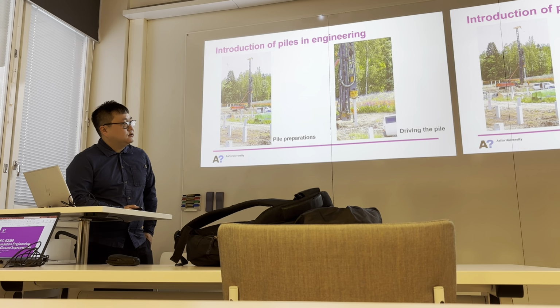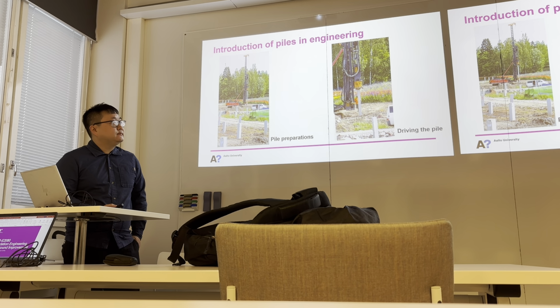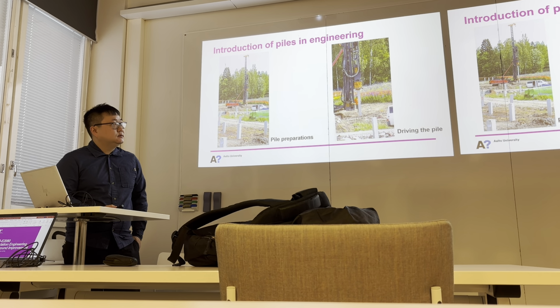One thing I want to comment on is the driving of this pile. You know that in Finland we have very soft clay soils, and when this driving is done, typically through this very soft clay, even though we say we are driving the pile, as can be seen at the beginning of this video, they practically push the pile through this very soft layer.